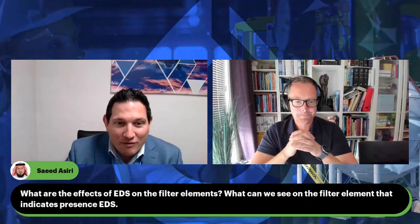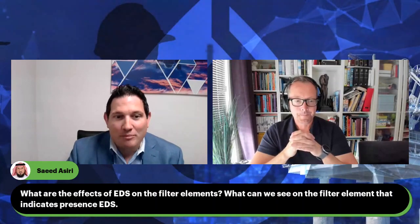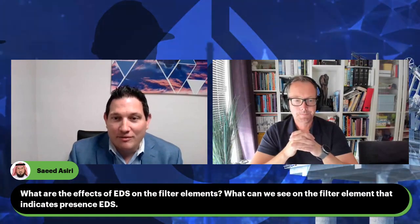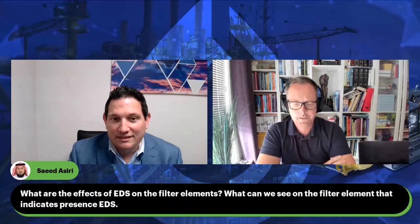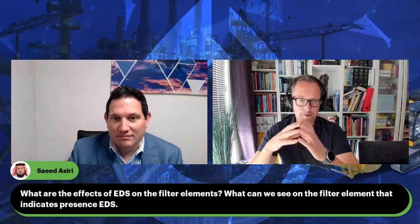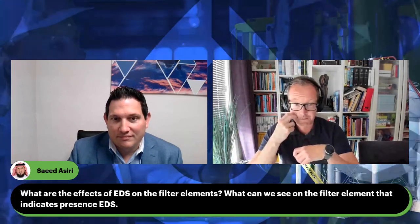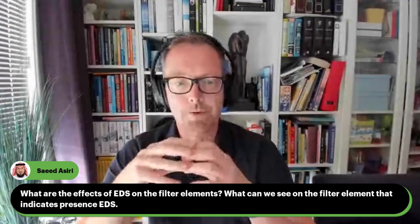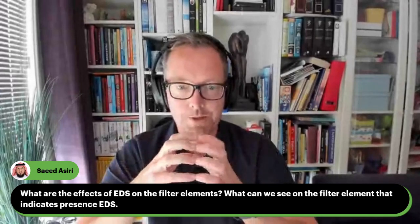Okay, excellent. And we have a question from Saeed. Thank you. So what are the effects of ESD on the filter elements, and what can we see on the filter element that indicates the presence of ESD? When we have looked at a couple of elements where we have heard that distinct crackling sound from the elements, what you see when you look into those filters with a microscope is burnt areas where the discharges have damaged the filters.